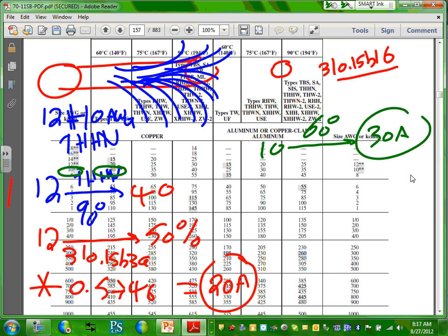If you did exceed, which could happen, say after you derate it you end up with 35 amps. Could it happen? Yeah, because we started with 40. We cut it a little bit and it became 35. Can I use 35? No. Why? Because the normal operating condition for this conductor does not allow it to carry more than 30 amps. Does that make sense? More than 30 amps.